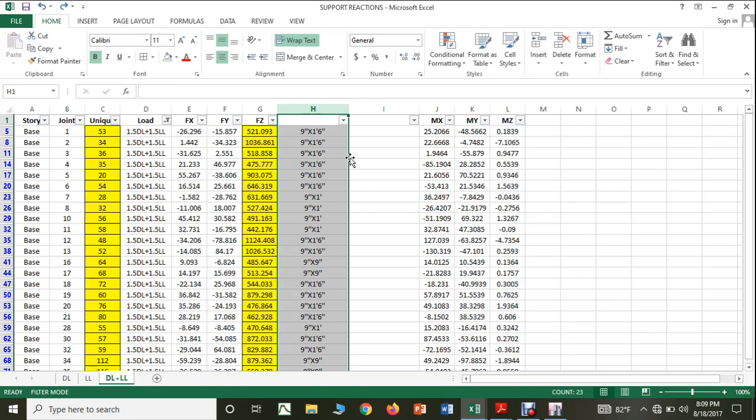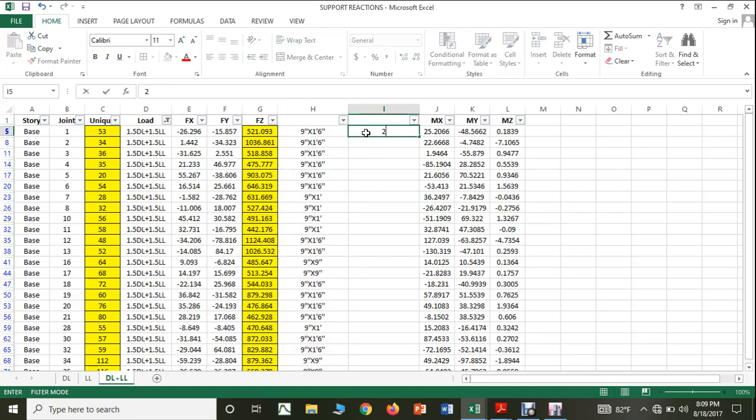Okay, 9 inch is 228.6, that is nothing but here 230. So 230 into 1 feet 6 inch, that we have to see when you convert. When I convert 1 feet 6 inch, it is 457.2. I can make it as 458. Okay, I can make the column dimension as 458.